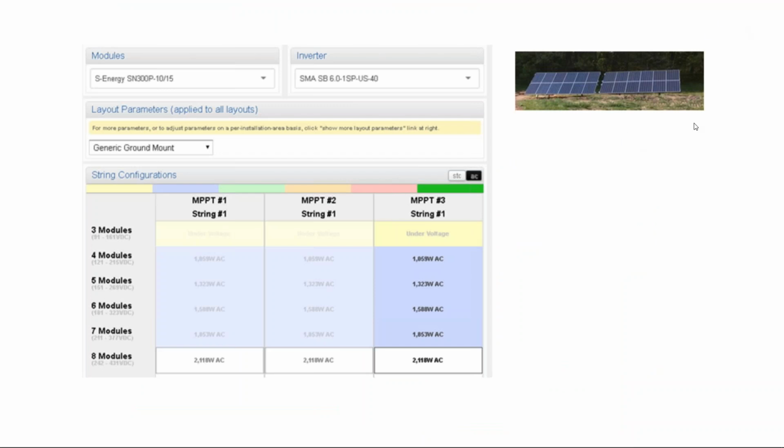In solar design, with battery lists, the manufacturers have sizing tools available on their website, and they're pretty simple. You use this module, this inverter, and it tells you how many modules can fit per circuit and how many circuits you can have. So I could do 7 modules, 3 strings of 21, or if I had a 12 module system, I could do 2 strings of 6, all using this particular module and this particular inverter.